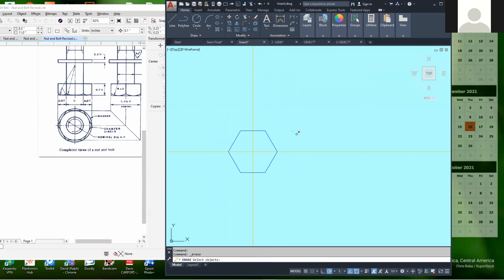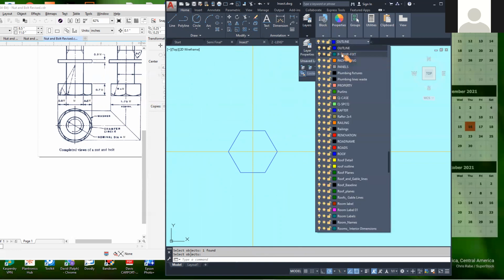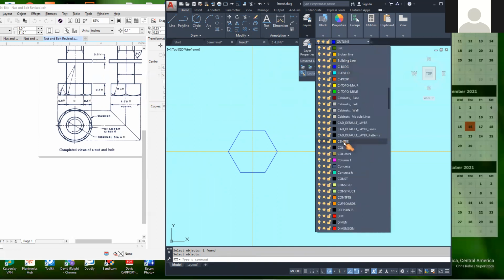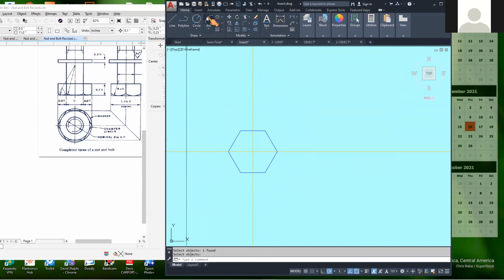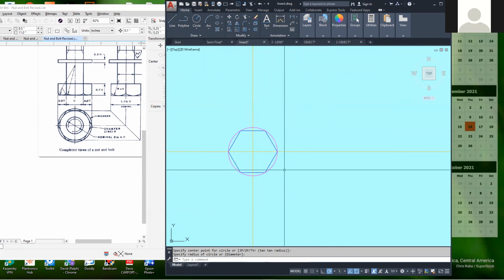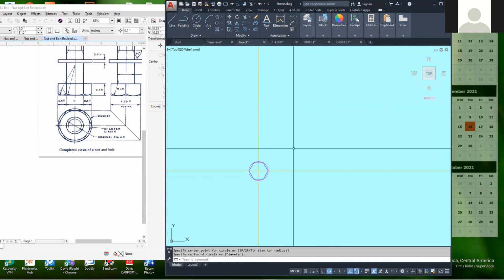All right, let's start over. The M is 10, so therefore you draw a circle twice. In the good old days, we would have had to draw the circle and put the hexagon on the inside of it. But as much as you have AutoCAD, you put the hexagon on the inside of that. So your hexagon would be on the inside of a circle, twice times M.